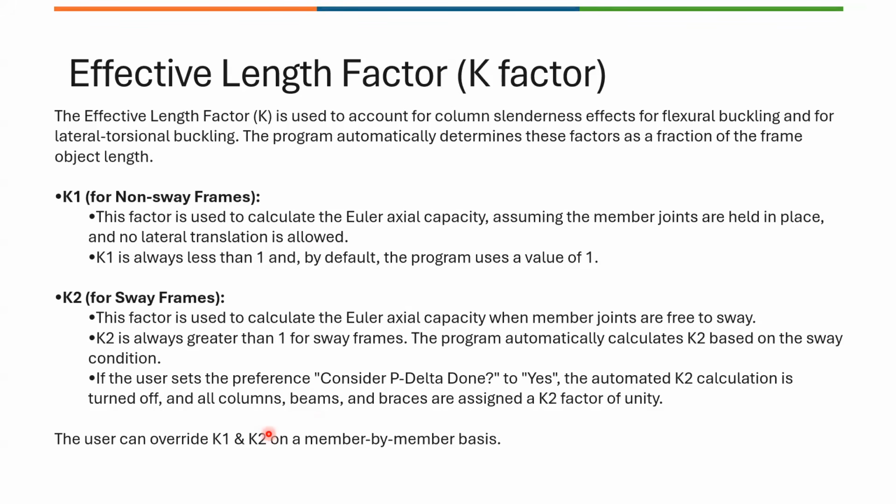And effective length factors, so K1 and K2, K1 is non-sway and K2 is sway. So the program calculates both and uses them as per the design preferences.